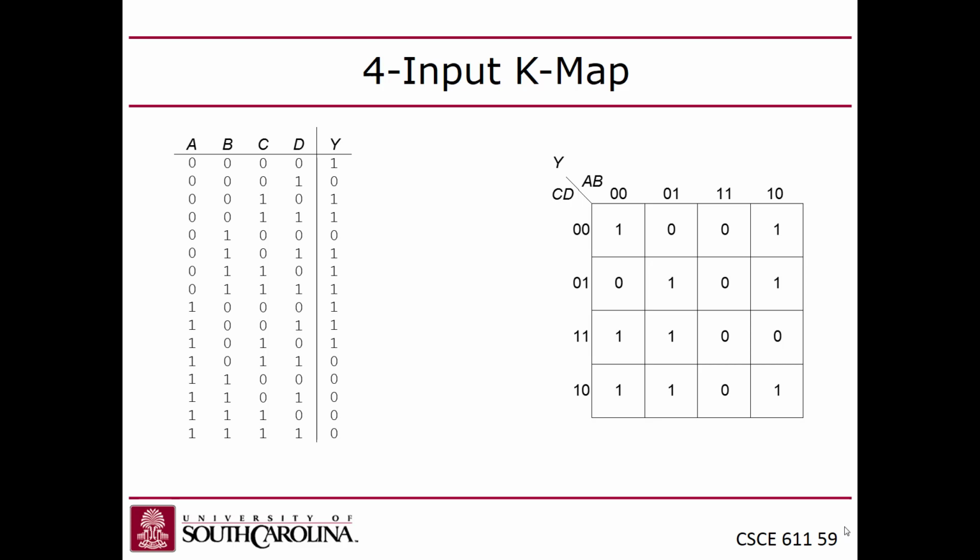So you'd have to have 4 of these 4x4 grids kind of in 3 dimensions, right? But you can do that. This textbook doesn't show any of those. The highest it goes is 4. But this also points out that Karnaugh maps are very limited. There's no way to go beyond 6 variables, as far as I know, right? Because you'd have to look at it somehow in 4 dimensions, right?